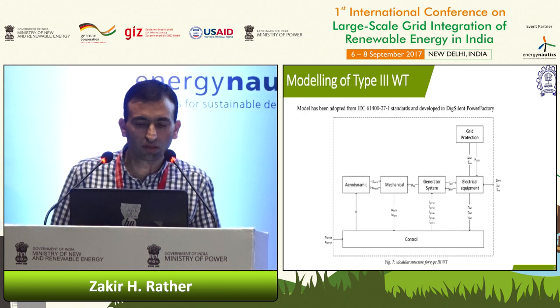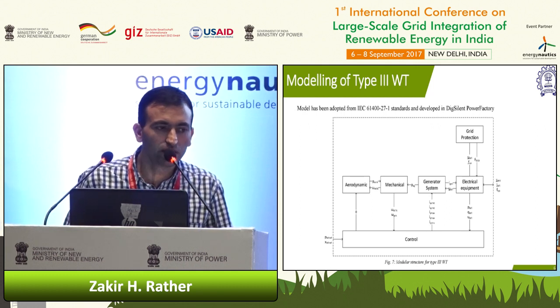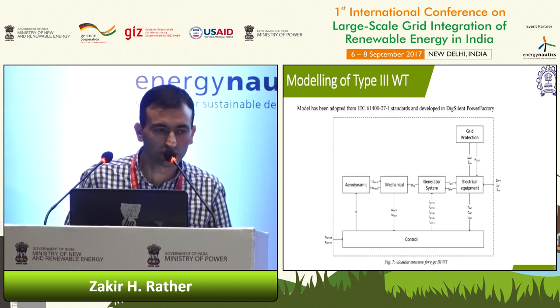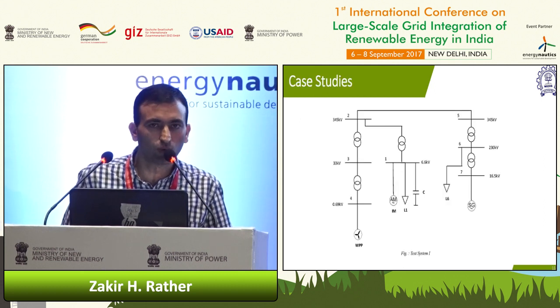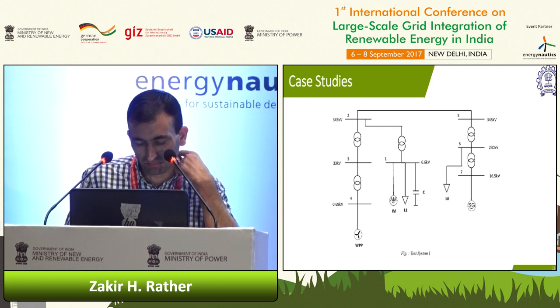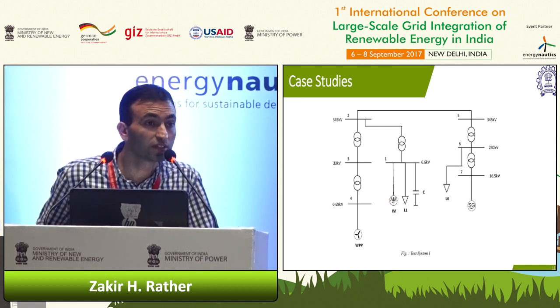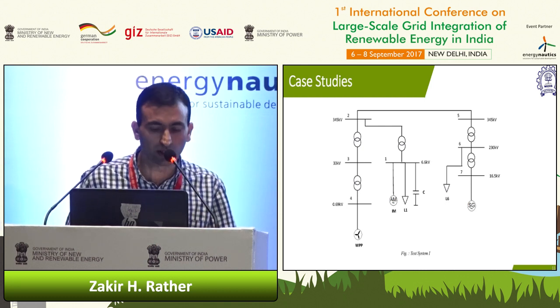This is a modeling of the wind turbine that we did. We implemented this Type 3 DFIG-based IEC 61400-27-1 model, and then we tried to see how it actually affects the system if we stick with this active power priority LVRT requirement.